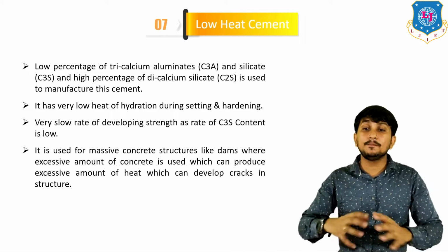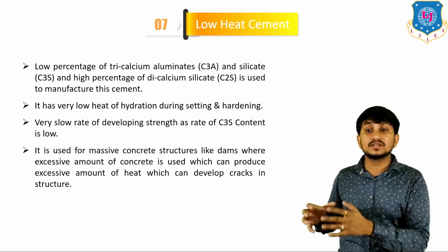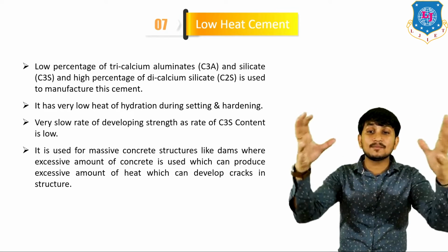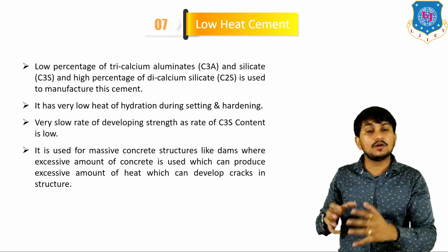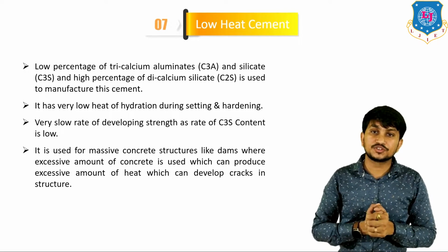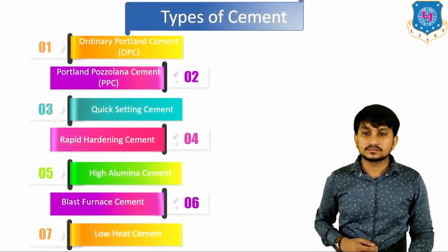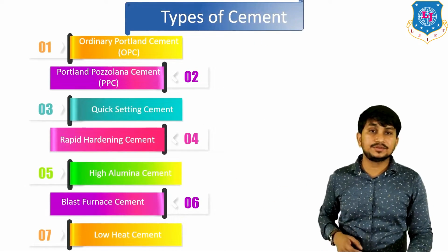It is generally used for massive concrete structures like dams, where an excessive amount of concrete is used, which can produce excessive amount of heat, which can develop various cracks in the structures at the initial stage. That's all about the low heat cement.